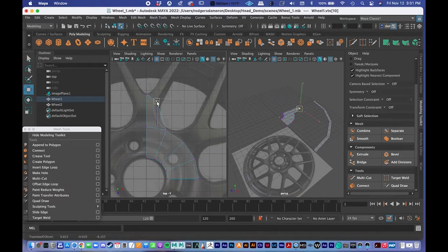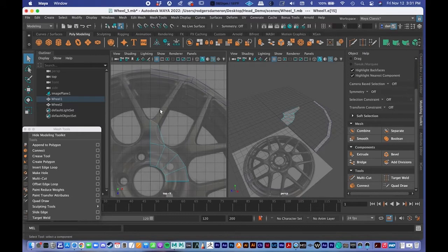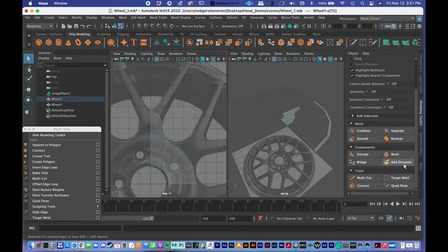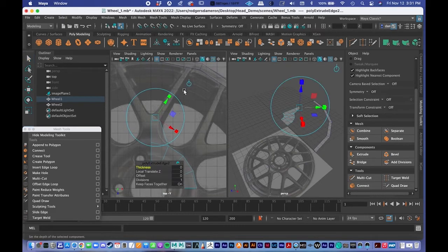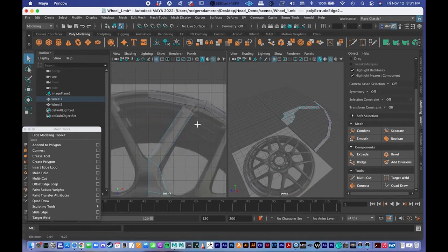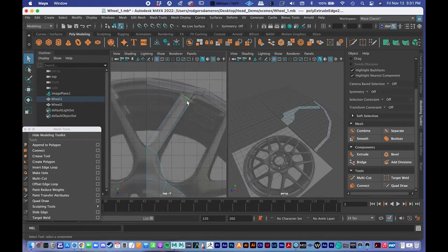So I'm going to position this, and the idea here is that I want to make it so when I extrude this edge, it'll move out in the direction of that inner spoke right there. So with that edge selected, I'll press extrude, and this time local's fine because we don't have to worry about symmetry right here because what we're modeling it after goes out in a different direction. So I'll just pull it out there, press Q. I always press Q pretty quickly just to make sure I get out of extrude.